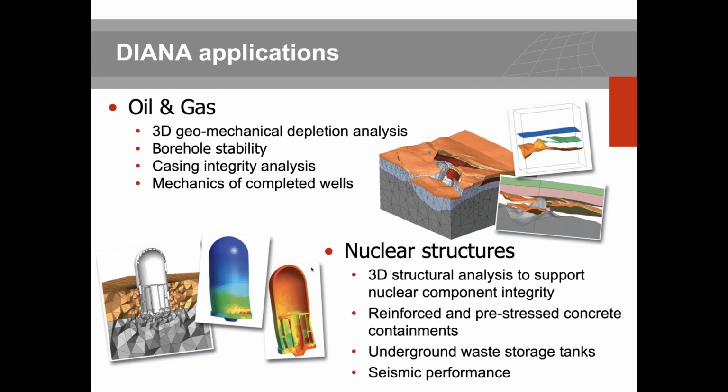Among the advanced types of application, Diana is very well known in the field of oil and gas and nuclear structures. Based on the type of complexity, you can simulate 3D geomechanical depletion, borehole stability, casing integrity analysis, and mechanics of completed wells.